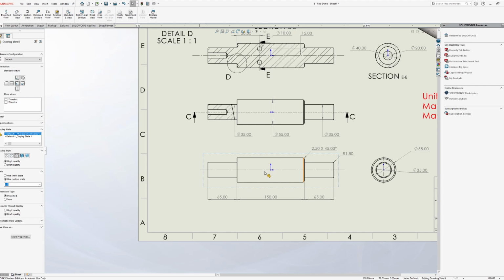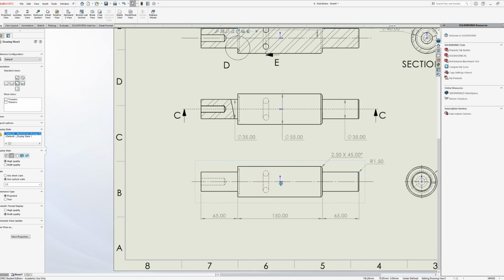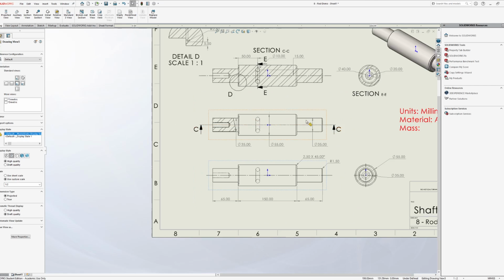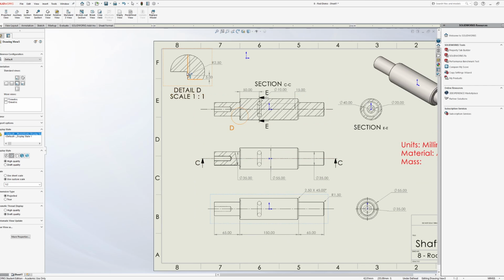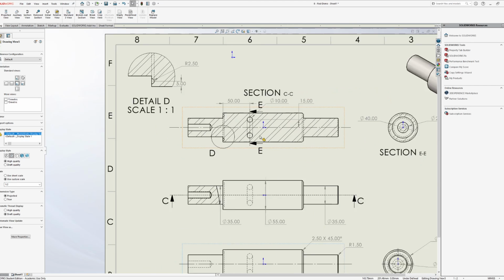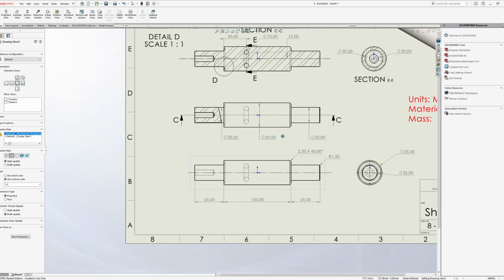So the option that I'm using there, it'll make sense if I click on this one instead here. If you look at your display styles, some of your display styles will give further information. So I'm using the one for that one that is hidden lines visible. This is actually also pretty good information. I could just have it on something like this or on something like this, and it gives a lot more information about what's happening on the inside there.